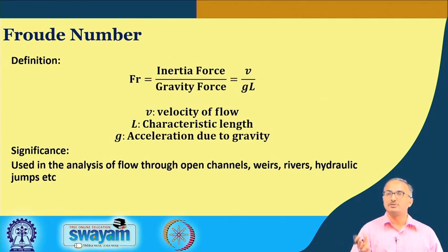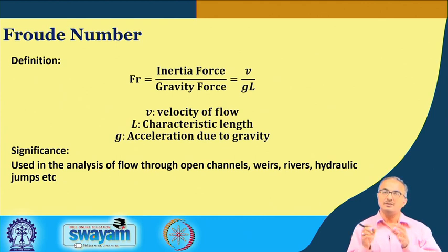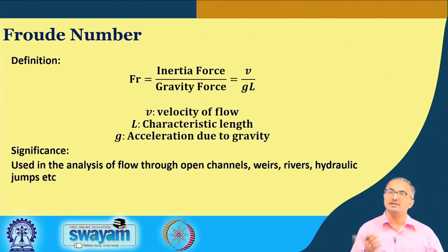And two-phase flow comes when a liquid, while flowing, gets evaporated, or a gas, as it flows, gets condensed. So in that case we get two-phase flow, or sometimes we also have one liquid flow and one vapor flow, and they are going together. In those cases also we have this effect of gravity due to the difference in the densities of the two fluids. Okay. Otherwise, in an open channel flow we have the Froude number, and we have to account for this effect of gravity.